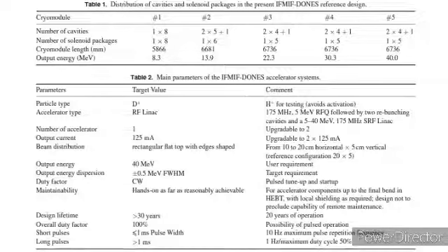high power solid state amplifiers with a CW output power level up to 200 kW, a total of around 54 such amplifiers are needed, one for each accelerating cavity and an additional 8 for powering the RFQ. Additionally, the MEBT is powered by two smaller solid-state amplifiers rated at 20 kW CW. The main parameters of the IFMIF-DONES accelerator system are described in Table 2.